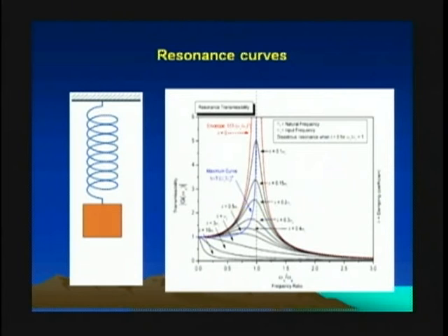When the frequency of the external excitation is 0, you certainly have 0 on the horizontal axis. And in this case, of course, the response will be static. That's why everything starts from 1, and the amplitude is equal to the excitation, or external force, which is 1.